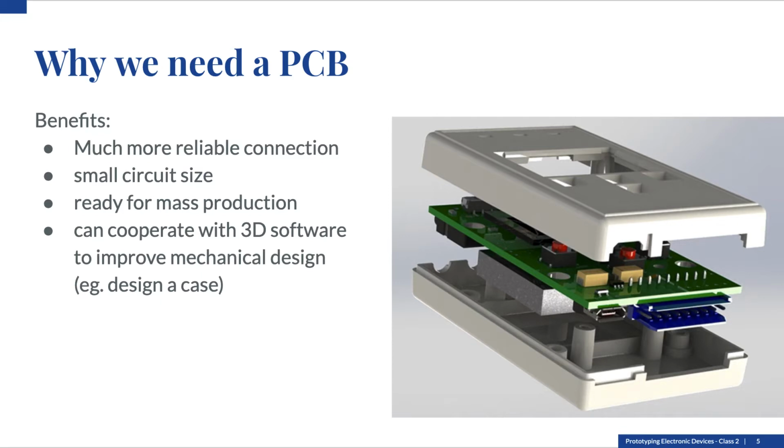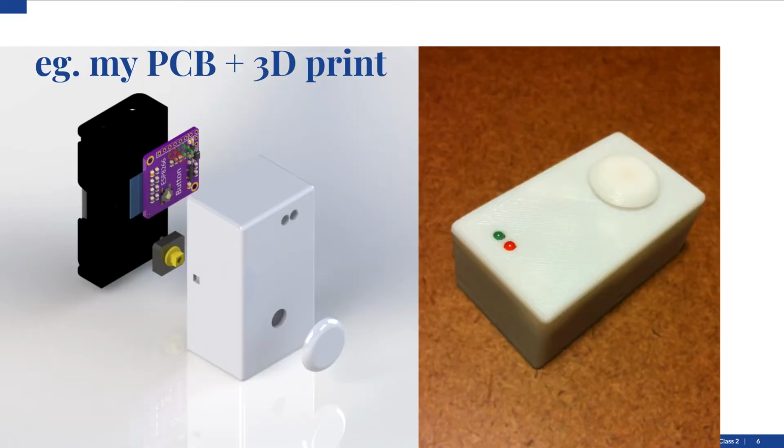PCB is a technology ready for mass production, and for most modern PCB software, we can export a 3D model of the board and cooperate with other 3D software, so the mechanical design will be much simpler. For example, here is the dash button circuit I designed. By exporting the circuit's 3D model and importing the model into a 3D design software, I made the case that fits the circuit precisely. On the left image, the purple part is the circuit.